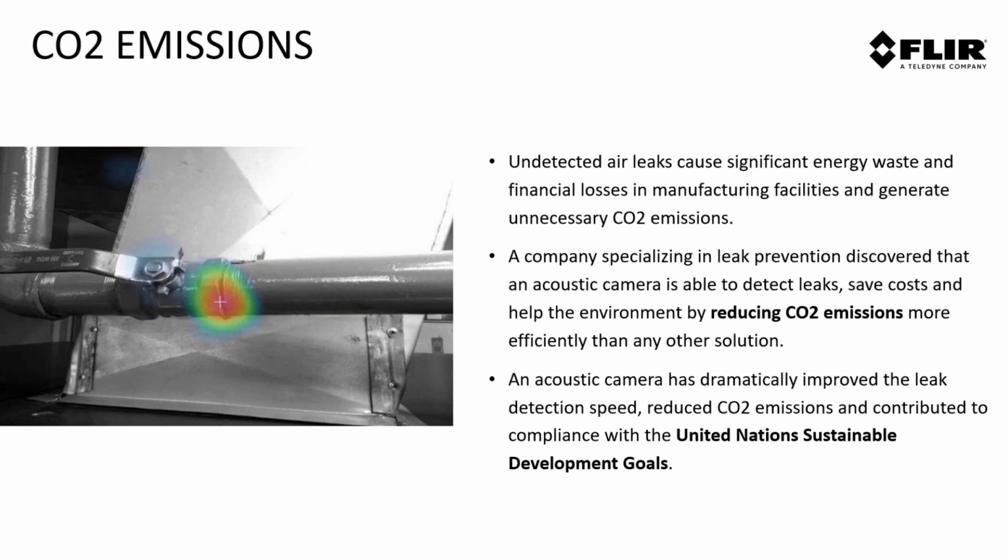We glossed over it a little bit earlier on the food and beverage side of things. With CO2 emissions, CO2 is very expensive, and being able to quantify and identify these leaks matters. There's one customer I worked with recently. We went in to perform a demonstration of the camera, and within 25 minutes found $11,000 of CO2 leaks in their facility.